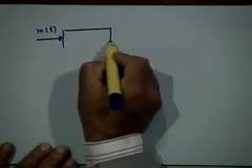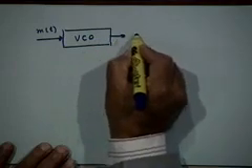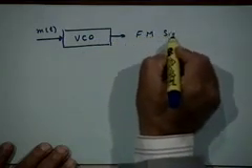Now, what kind of system will this be? Frequency modulated signal or PM phase modulated signal? If I use a voltage controlled oscillator, this will give me FM or PM? Frequency modulation. Can I use it for generating PM? Just think about it. Here is a message signal m(t). Good, very good. He has suggested the answer. So if I apply m(t) to a VCO, I'll get an FM signal. Right? This is what you are saying.